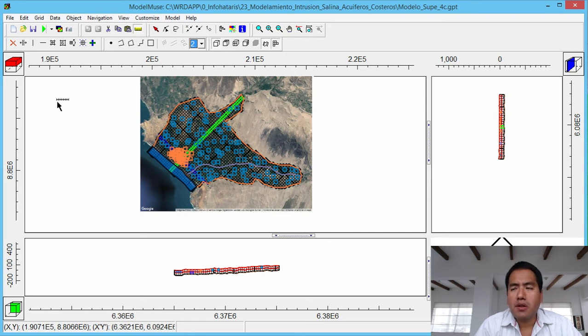From my personal perspective, if you wanted to do it in a more scientific or more commercial way, you would need a higher spatial resolution, maybe 50 by 50, in order to better define the seawater intrusion problems and the pumping effects. Yeah, why not? This could be a good approach. The problem is that it will require more time to process, it will be more unstable, you will have more crashes, and the output data will also be bigger. So for this tutorial we use just 200 by 200, instead of 50 by 50.